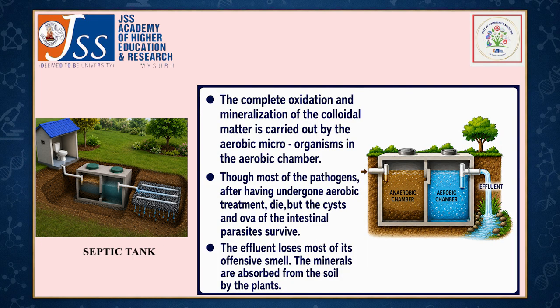The complete oxidation and mineralization of the colloidal matter is carried out by the aerobic microorganisms in the aerobic chamber. Though most of the pathogens die after having undergone aerobic treatment, the cysts and ova of the intestinal parasites survive. The effluent loses most of its offensive smell. The minerals are absorbed from the soil by the plants.